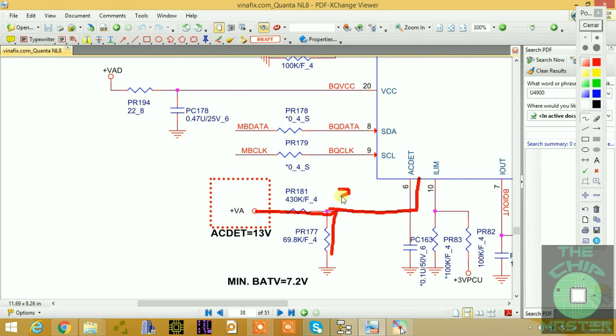So this is about 3.1 volt after conduction, right? If you have your voltage divider calculator, you can calculate. This is 18.6 volt, right? So the formula is resistor 2 divided by R1 plus R2. You should know your formula, but you have calculators which can calculate this voltage for you, and this is coming through a pull-up resistance to 3.1 volt, right?